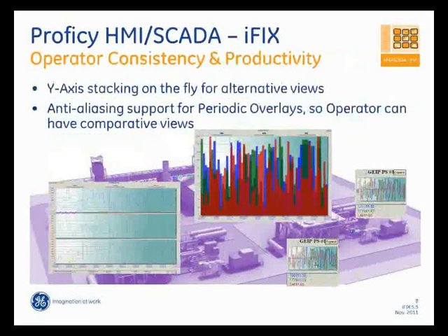The other aspect that we added to the new charts is the ability to stack y-axes. So if you have like this chart object that we just saw, if you have multiple pens on a single chart, and at some point if the chart gets very noisy and you want to divide that chart into individual pens so that you can get a better view of how those charts are stacking up, now on the fly, the operator can choose to stack the y-axis. So it takes each pen and creates its own chart. It divides that particular trend object into the number of pens it has and creates individual charts for those pens.